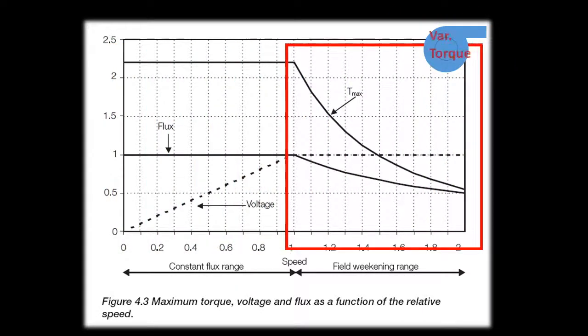If the motor speed enters the flux weakening range, full voltage is fed to the motor and torque will drop off with increasing frequency. Using a motor in this region can be seen as a method of supplying a process with variable torque control via VSD.